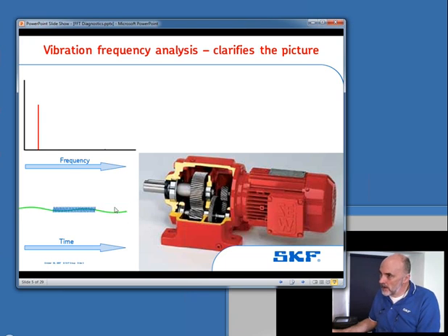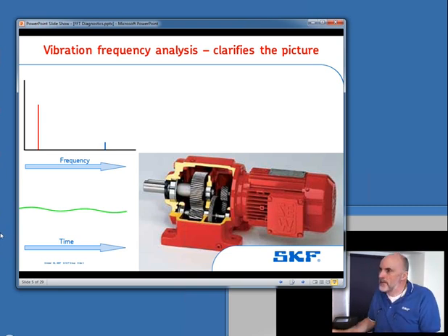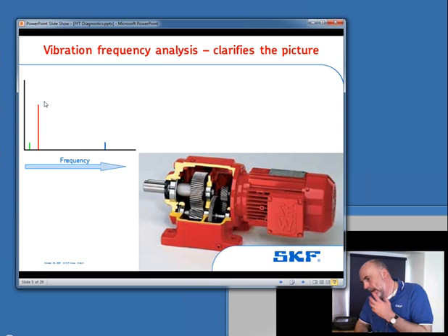So the process goes on. For each and every sine wave in our spectrum, if we're looking at a 1 kilohertz spectrum, the fast Fourier transform is going to use this trigonometric transform to break the signal back down into its constituent parts. So each peak in the spectrum is representing something that is rotating or radiating forces at that frequency. And the objective of this session is to show you how to recognize patterns.